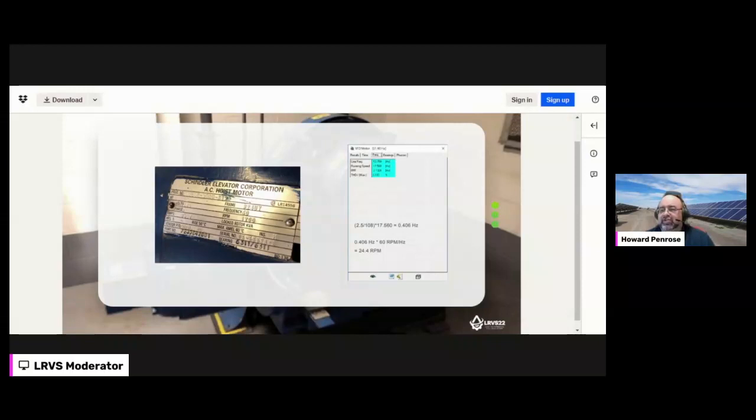So usually what we do is identify one or the other, using vibration or another technology after we've detected a problem, so that we just focus on the one with the problem. In any case, in this case, we know the output speed at peak 60 hertz is 24.4 RPM. However, it's a variable speed application with people on it, so it doesn't immediately go from 0 to 24 RPM. Otherwise, you'd have broken ankles and bonked foreheads. Next slide, please.